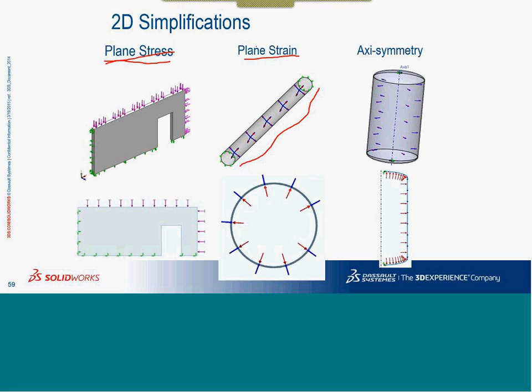These are the three idealizations that are happening. Axis symmetry is the one that we are going to use today. Typically, those which have constant cross section in the circular direction can be represented by using such a cross sectional entity only, and the simulation can be actually done on the entire setup or cylindrical part. One point to remember, it is not only the geometry, but even the loading and boundary conditions should be symmetric. If not, it goes haywire.